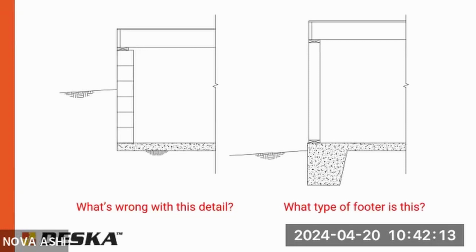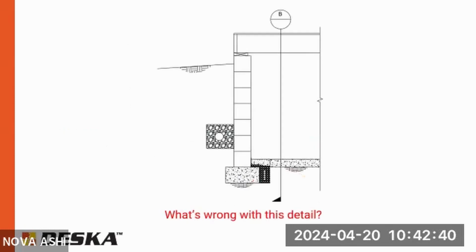Last couple here. On the left here, there is no footing. That's a problem. We'll usually see this with carports and things like that, but sometimes some older foundations just didn't install footing at all. And then this is another example of a monolithic footing where the grade's at the proper height, not touching the timber framing. What's wrong with this detail here? Exactly, the drain tile's too high. The drain tile needs to be below that slab, otherwise you're going to have water sitting in that void, up against the foundation wall.